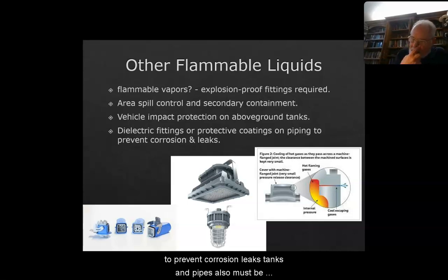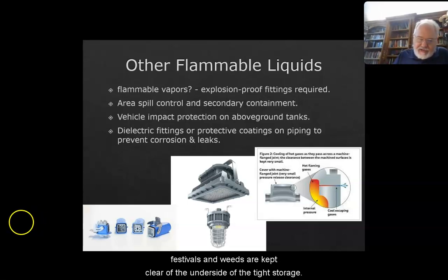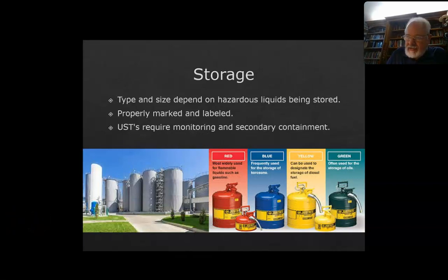Tanks and pipes also must be protected from galvanic action and corrosion by installation of dielectric fittings or protective coatings. If tanks are situated on permanent foundations, the foundation system must be at least 2-hour fire-resistant rating, and the inspector should make sure the combustibles and weeds are kept clear of the underside of the tank. Storage. Type of storage vessel and size depend on the hazardous liquids being stored. Tanks must be properly marked and labeled. Underground storage tanks require monitoring and secondary containment for leaks.